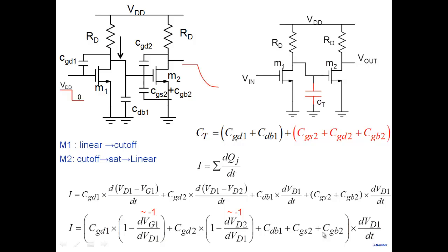All right. Because of analytical calculation, we want to get an equation, so we're writing it in this particular form. Accurate values of delays, which take into account all the changes, will have to come from simulation. But as a first order analysis, you can see why one is writing it as I equal to a single capacitor here.